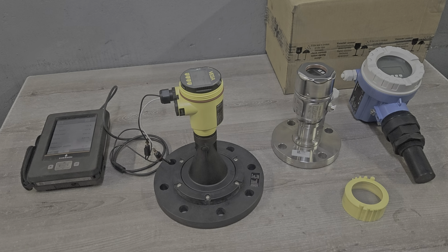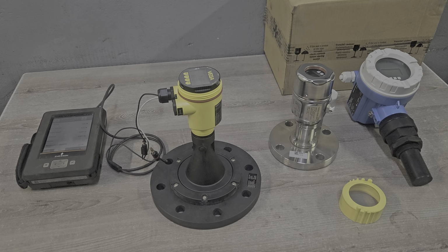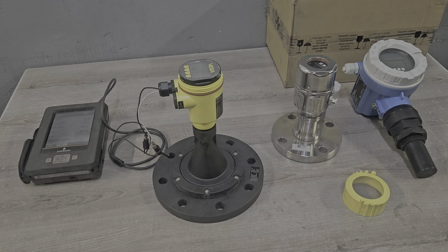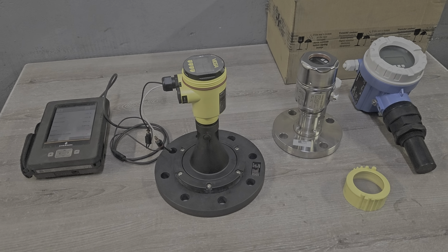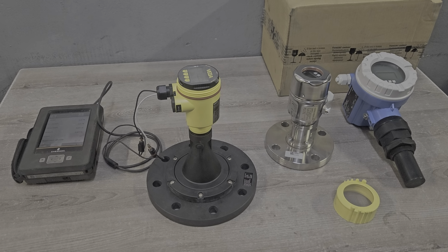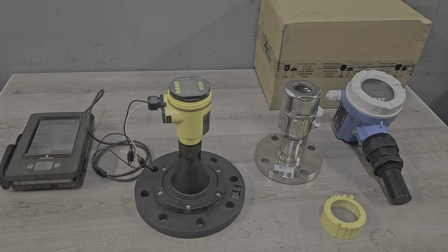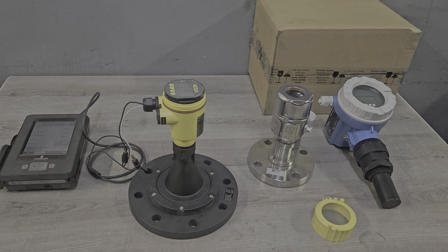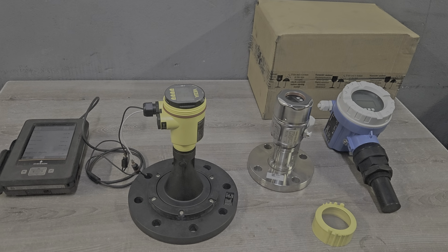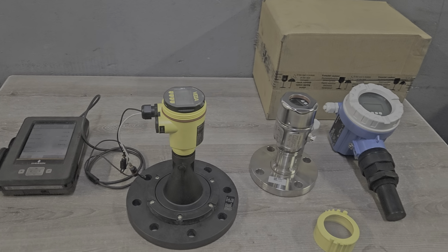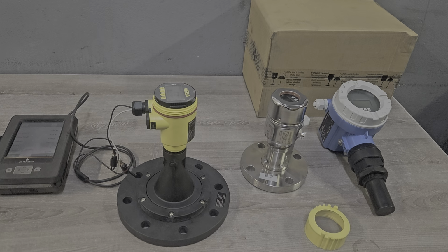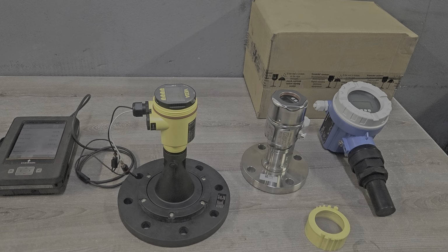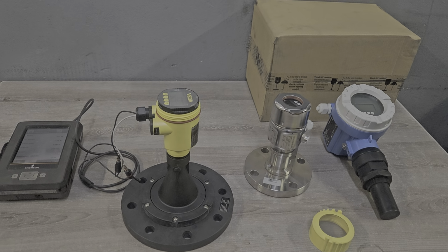We know in radiation we've got various types of radiation and a very wide spectrum of radiation, from gamma rays, ultraviolets, we've got different types of radiation. So this level transmitter is based on that principle. So it will send a light wave, and then the time it takes for that light wave to travel and to hit an object is equivalent to the level, to the distance.